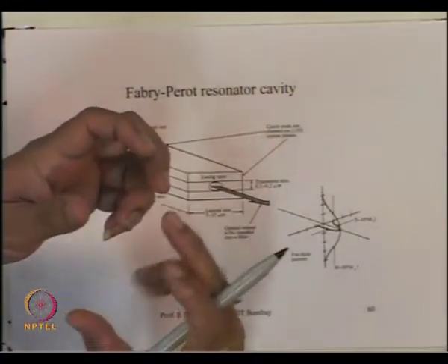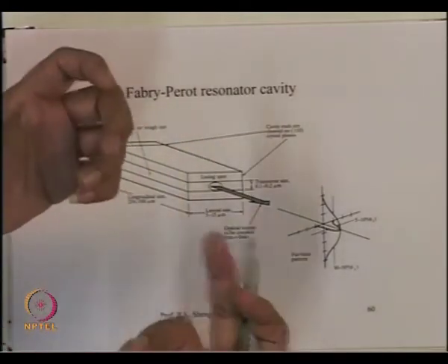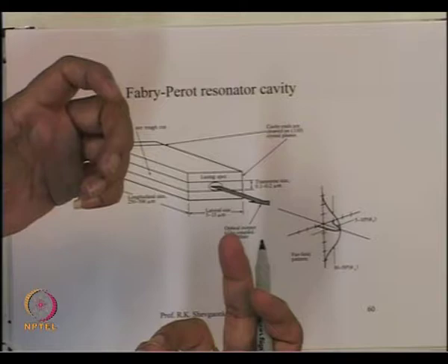After the current crosses the threshold value, suddenly the process turns into the stimulated process. So, the angular cone is no more 180 degrees, but suddenly gets narrow like this. So, from this direction it looks as if the device is switched off, because now the radiation is going into a narrow cone. Then I have to orient the device properly and look into it to really see the radiation coming out of that.